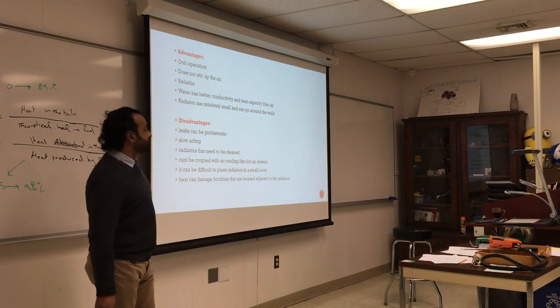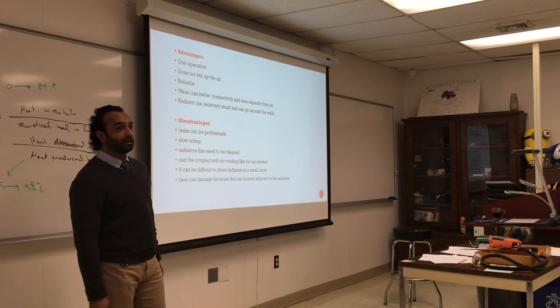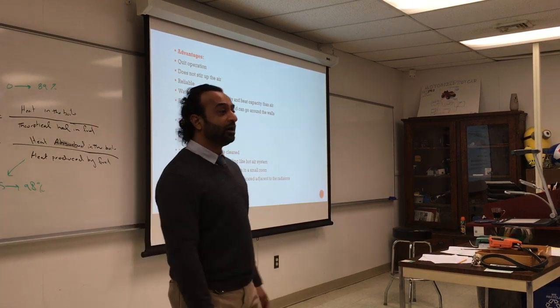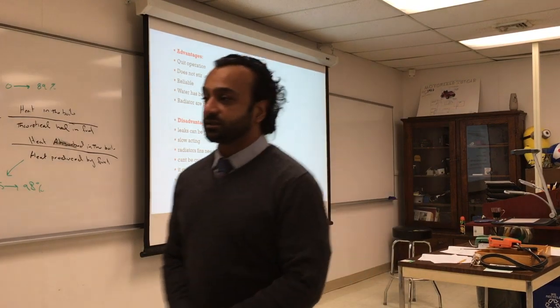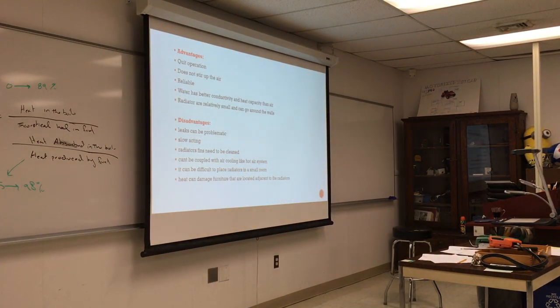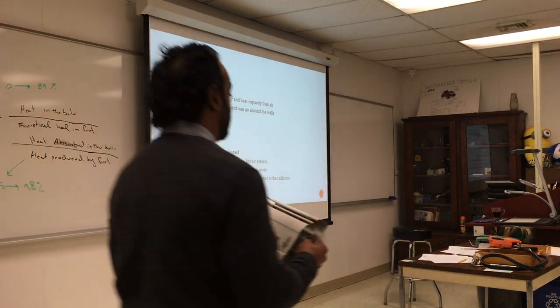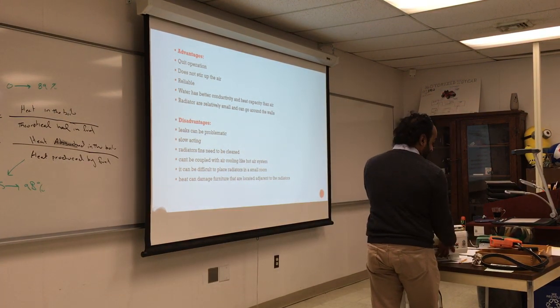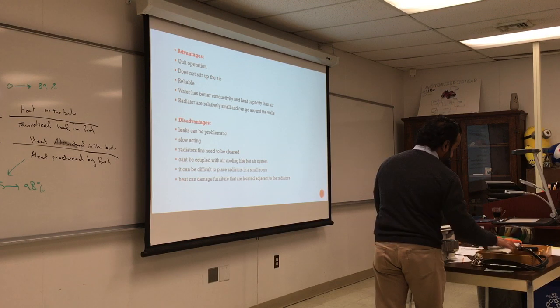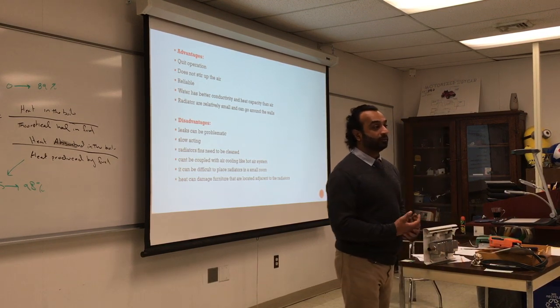Radiator fins need to be cleaned. We talked about that before, right? And this is some of the maintenance that will be required to have good efficiency. If the fins over here are not cleaned periodically, they will accumulate a lot of stuff. The air circulation is not going to go very well. And the radiator will not perform.